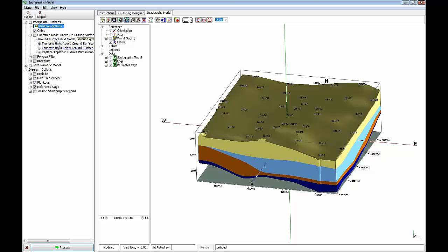You can actually also use a grid file to clip the base of your model as well. So if, say, you have kind of a planned excavation and you want to predict what kind of materials you might encounter during the excavation, you could actually clip a model from below as well, and that would just give you volumes of potentially excavated material.